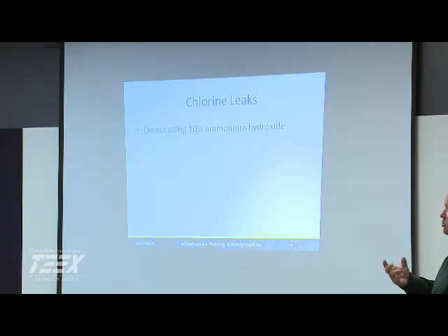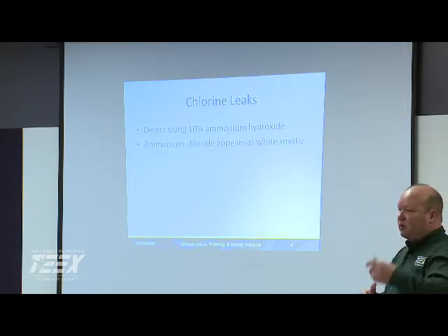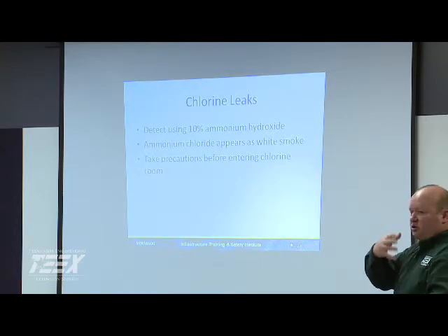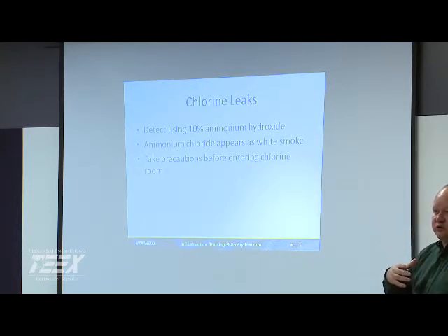If we have a leak, we're using ammonium hydroxide. We don't want to spray it on there, but we want to use the gas coming off. It's going to be white smoke if you have a leak. And are y'all using masks whenever you do changeovers and stuff? We have them. Okay.